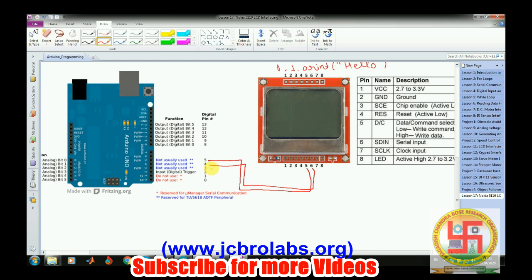Then pin number 3 is connected to the serial clock, which is pin number 7 of the LCD, and the backlight is connected to 3.3 volt. Pin number 6 of this Arduino is connected to the reset pin of this LCD, which is pin number 4 of the LCD. And pin number 7 is connected to the chip select, which is pin number 3 of the LCD.